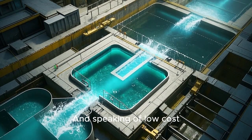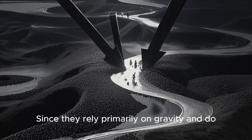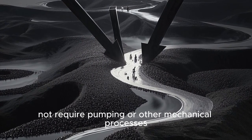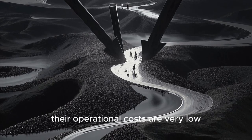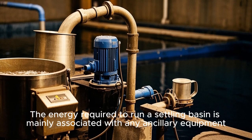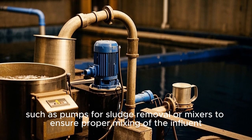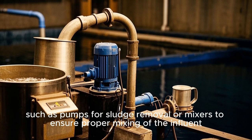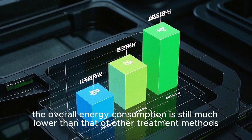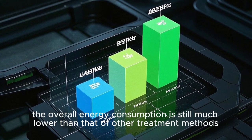And speaking of low cost, another positive is that they are very energy efficient. Since they rely primarily on gravity and do not require pumping or other mechanical processes, their operational costs are very low. The energy required to run a settling basin is mainly associated with any ancillary equipment such as pumps for sludge removal or mixers to ensure proper mixing of the influent. However, even with these additions, the overall energy consumption is still much lower than that of other treatment methods.